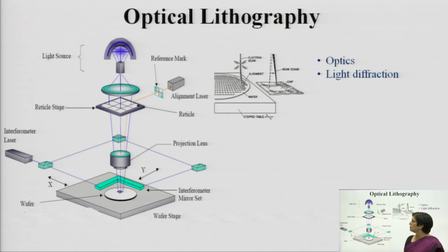Now, what is this optical lithography system? Here you have a light source, and you have the mask. Here this is called a reticle stage. The reticle stage is nothing but you have vertical alignment lines, just like on your CRO you have lines. Here, to have the mask alignment precisely, you have these lines made, so that your pattern transfer happens precisely through this.